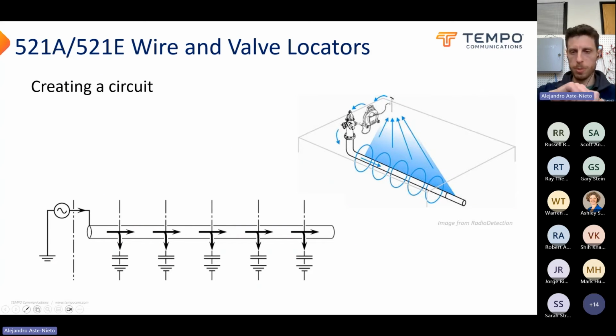If you strip the far end of it, wrap it around a screwdriver, and stick it in the dirt, that wire's going to have no problem carrying signal, because now we have a full circuit. We have wire going out through the wire, returning through the far end where it goes in the dirt, back to our ground stake.